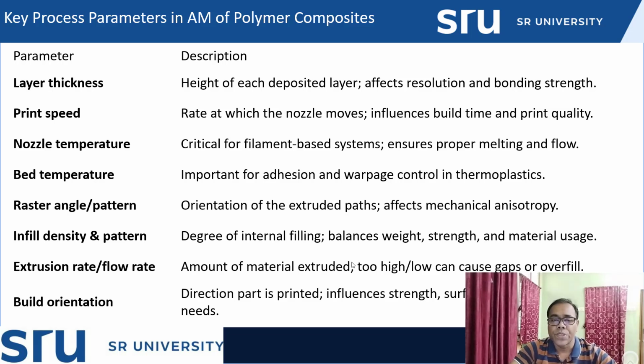Similarly, coming to the infill pattern, it can be of any profile inside the printing process. It can be triangular, cubical, hexagon, pentagonal shape, or a honeycomb structure. That is the way the printing pattern will come. One has to know what the printing pattern is. If you choose one pattern, from one pattern to another the mechanical property will change because the inside infilling will be different.